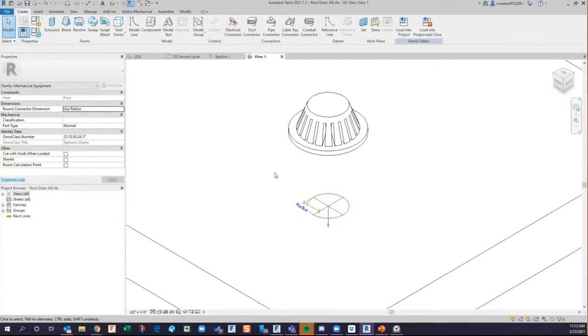Now, the first thing I need to do is insert a point that the total station can read. I'm going to use our product called Evolve Mechanical to do this. We actually give a Trimble point out. If you have other third-party software, look for their point, and you can add their point if you need to, to your Revit for Fab database.